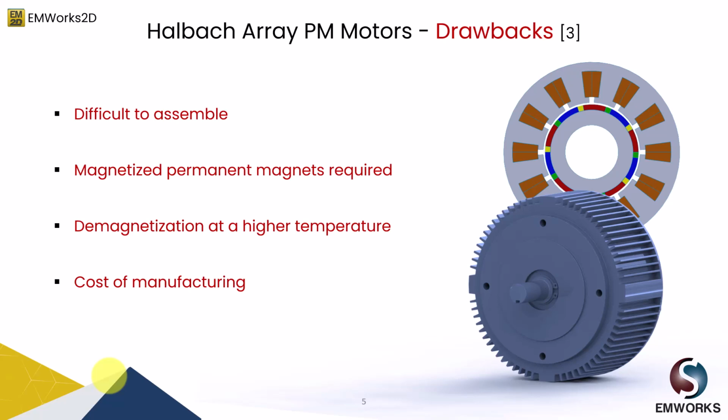Another disadvantage is that the magnets are arranged in direct or quasi-direct repelling conditions. This means the magnets in the same array are acting to demagnetize their neighboring magnets. With a high coercivity alloy, this may not be an issue unless high temperatures are required in the application. So basically, as the operating temperature increases, a magnet becomes more susceptible to demagnetizing, and neighboring magnet demagnetization occurs.